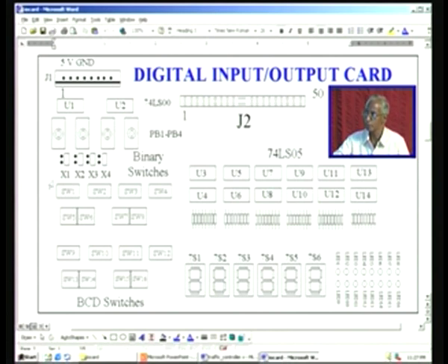And in parallel to switch 1 is the BCD switch, which is SW5, and this is graduated, as I mentioned earlier, from 0 through 9. You can use either the push button switch or this DIP switch for binary setting, or the BCD switch for the decimal setting. And all these are BCD switches, 4 numbers here and 4 numbers here down, all symmetrical, it is very easy